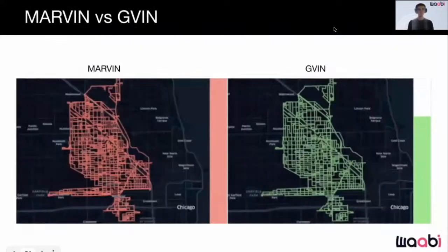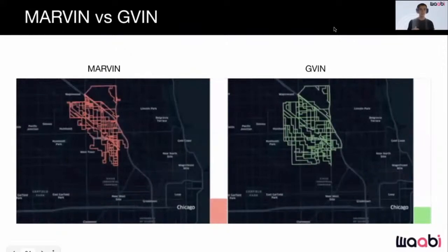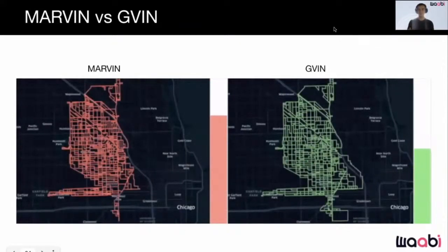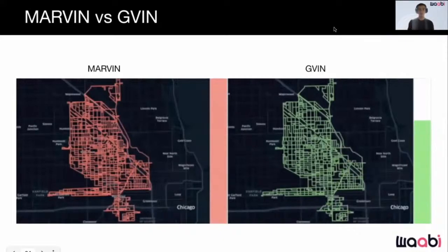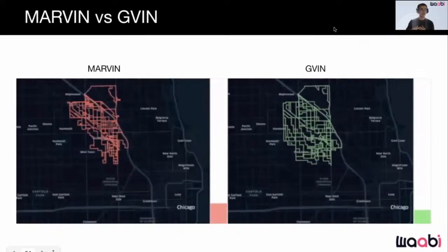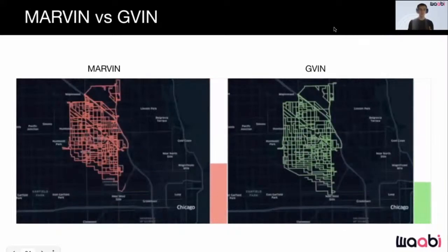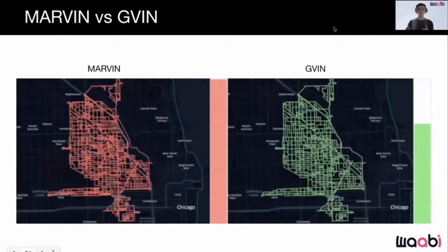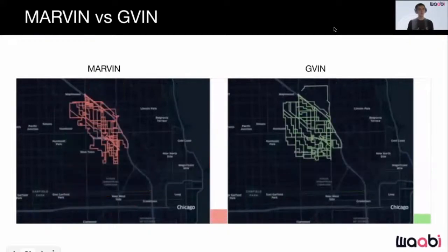We qualitatively compare the mapping process of Marvin to that of another competitor architecture, specifically that of the generalized value iteration network. We found that Marvin results in more thorough mapping processes, where we prioritize filling in all of the regions completely over exploration. Due to the mapping failures that can occur, and the lack of information where these failures are a priori, ensuring completeness of a region becomes a non-trivial task in itself.